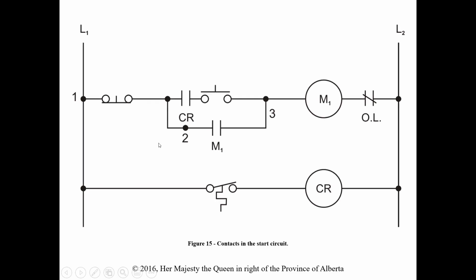Okay. Now we talk about, well, we moved it into the start section. So we're not in the stop anymore, we're in the start. Here's the hold portion and here's the start. So we look at it again with these contacts open and closed. If they're open, can I start this motor? And the answer is no, because I have a break here, so if I press start, nothing's going to happen. So it definitely affects the starting.